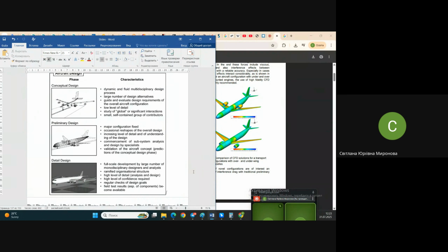In particular, what might the auxiliary purposes be? The anti-icing system supporting the flight. In military aircraft, it's usually solved not by the engine, but by using special electrical heaters and so on. In passenger and cargo airplanes, it's a more popular decision to use hot air from the engine. When it comes to the conditioning system, for instance, or some other systems, the power plant also takes part in all these systems.